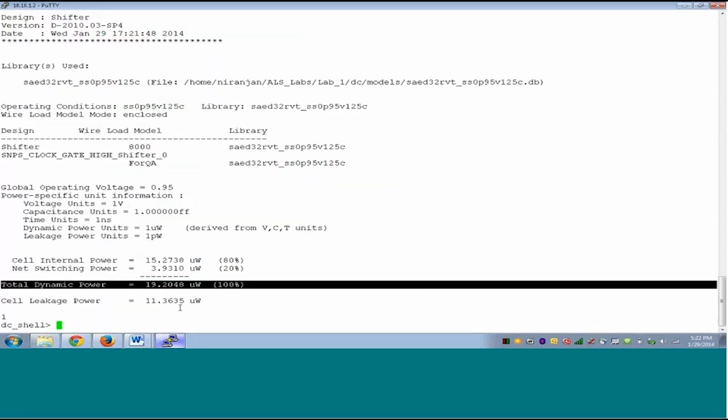And please note this is a very small design. It's just 8 registers, that's it, right? When you expand it to a very big design, I have seen in my experience designs that are very big, with 600k instances or even a million instances. They have like 100k registers out of those. Such designs will have gating percentages of up to 80-90%. That means 80 to 90% of all registers are gated. Imagine the power saving there.